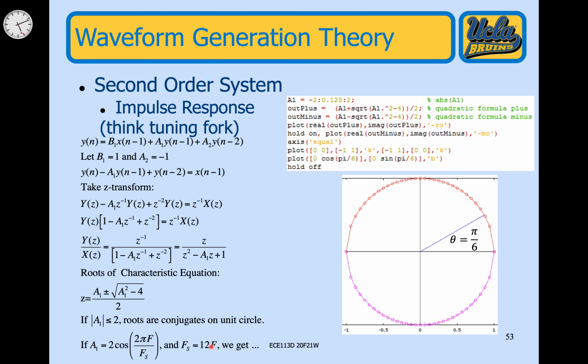And that's great, because it's following the sampling theorem. All you need is 2 samples per cycle or more to be cool with the sampling theorem. So you can call this angle theta. And here the value for theta equals pi over 6, which would be for a frequency where 2f over fs equals 1/6.